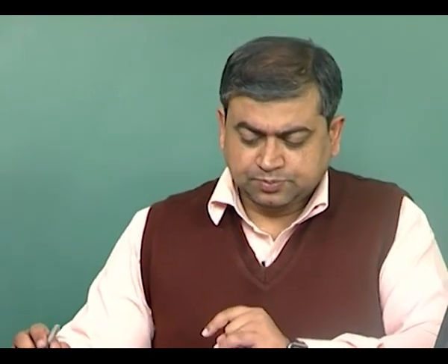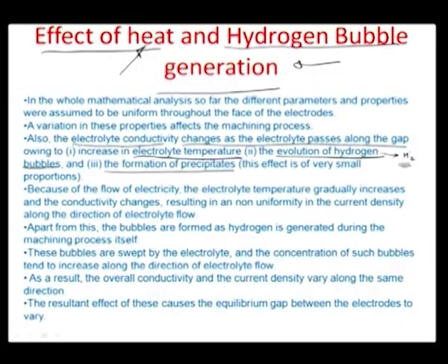This would have its own connotations because it would impose a change in local conductivity because of circulation of this small debris, so called precipitate, which is coming out into the ECM electrolyte. Although that precipitate effect is very small in terms of change of overall electrolyte, you do have to consider it, and particularly for microsystem design or microsystem fabrication, this may be a very important aspect: the changes of conductivity because of precipitates of all sorts of materials.